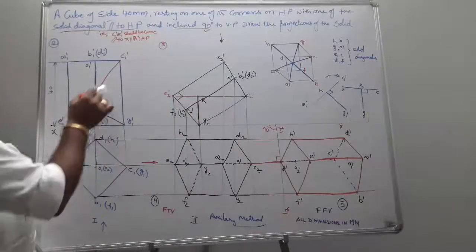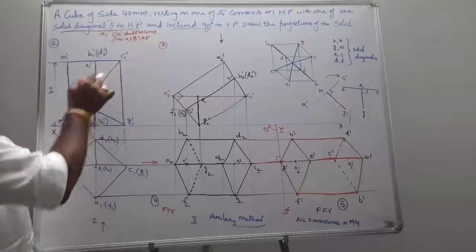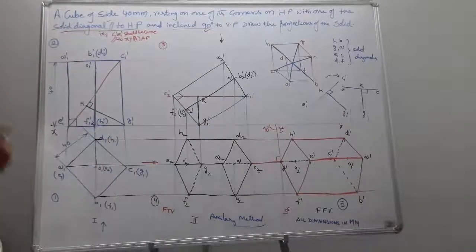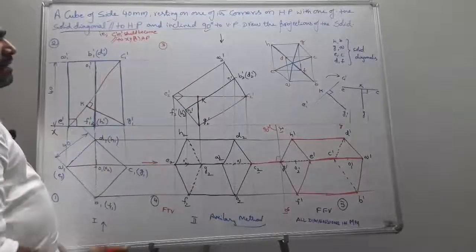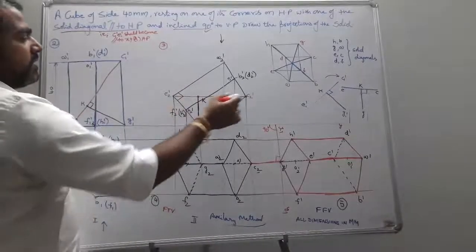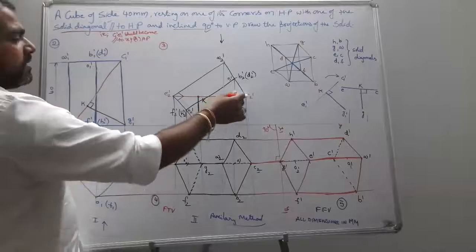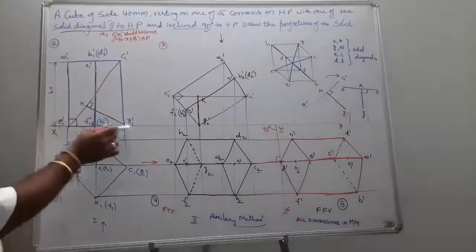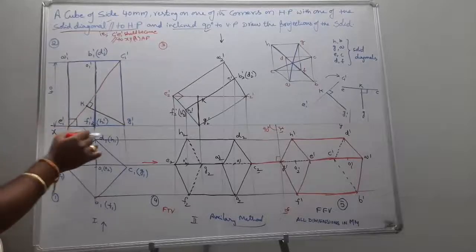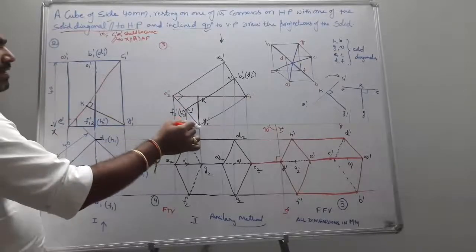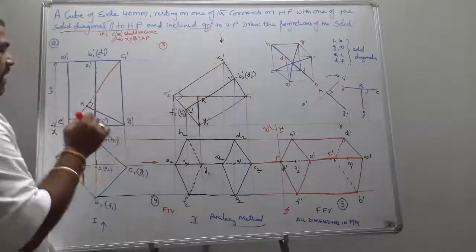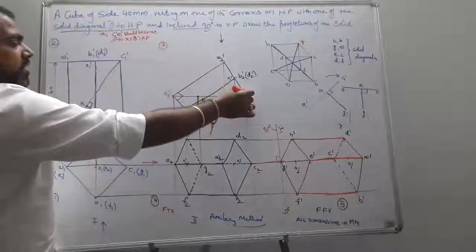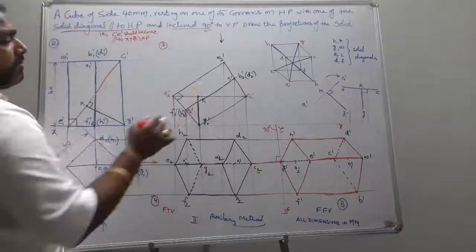From K, I draw a line parallel to XY and reconstruct the figure. So EC is placed. When EC is placed, I join C with G and E with G. I know that EG and EA are perpendicular, so I draw the perpendicular to G from E, measure EA and draw an arc. I get A2, join A with C, and obtain the remaining points.